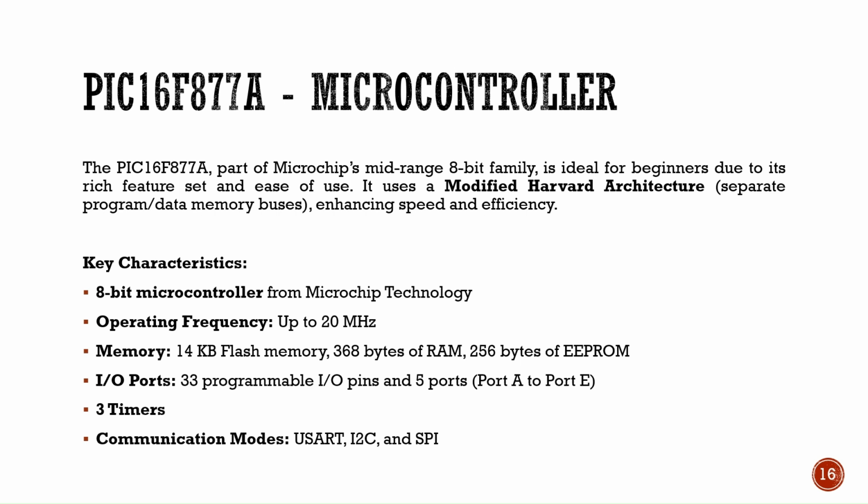Key characteristics: 8-bit microcontroller from Microchip technology, operating frequency up to 20 MHz, memory 14 KB flash memory, 368 bytes of RAM, 256 bytes of EEPROM, I/O ports, 33 programmable I/O pins, and 5 ports, port A to port E, 3 timers, communication modes, USART, I2C, and SPI.